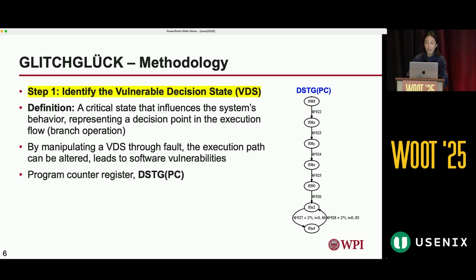Okay, so we can see that at the node, there are some instructions being executed. We don't know which instruction, but there are instructions being executed. And we can also know at what clock cycle each instruction is executed. Very interestingly, you can see that there's a while loop happening at the end of the PC instruction, meaning that if I can see this, I know that my countermeasure is effective because it entered a while loop.